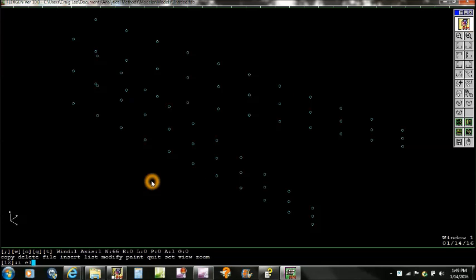Now we're going to insert a solid element. All of the elements in this model are solid. Element property 1 not found, we'll insert that. Material property, we need to create that. We're going to go with standard material 101, which is a glass aluminum ceramic. And a little bit more information. And we have to put all the elements in a group, so we'll create an element group called disk.